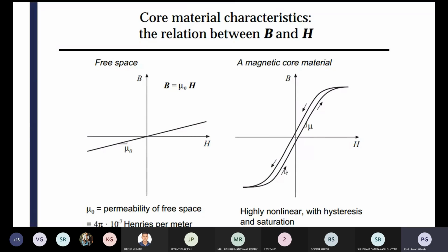So how do you reduce that loss? The only possible way is the selection of the magnetic material. Which type of ferromagnetic core you are using in your switching converter depends totally on the selection of the material. If you use a ferromagnetic material, hysteresis loss will always be there in any application, any converter, but how small the area is, that is the most important issue.